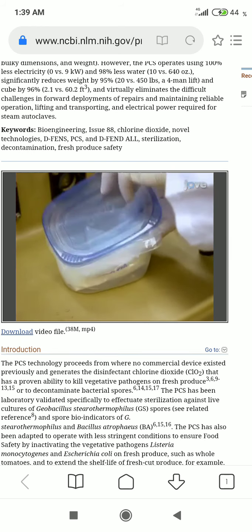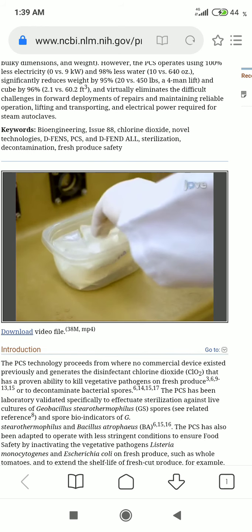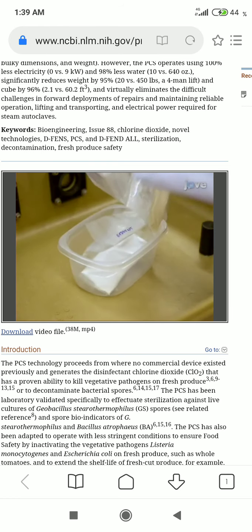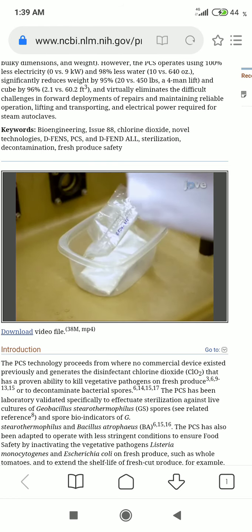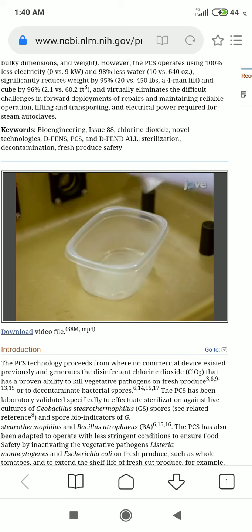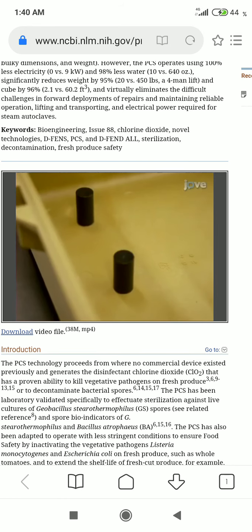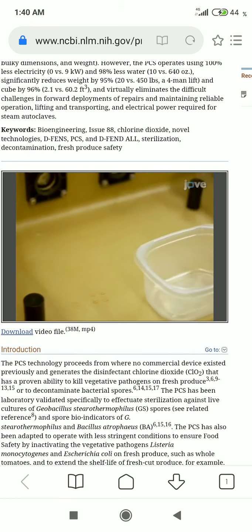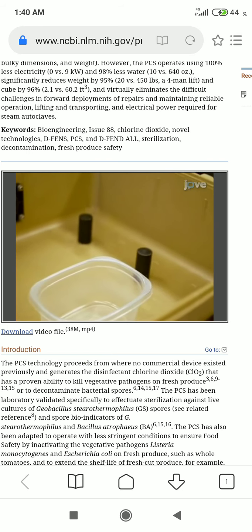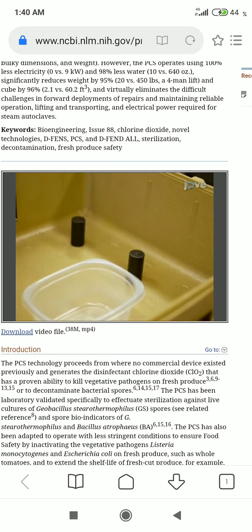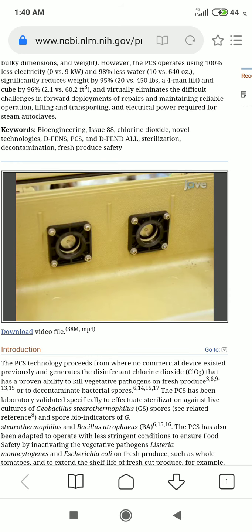The PCS is set up with a wide-mouthed reaction vessel that serves as a receptacle to receive and mix dry chemicals with water to generate sterilant. Four stilts attached to the base accept trays of surgical instruments or other microbiologically contaminated objects. And two check valves installed in the suitcase wall relieve potential pressure generated by the chemical reaction during the sterilization